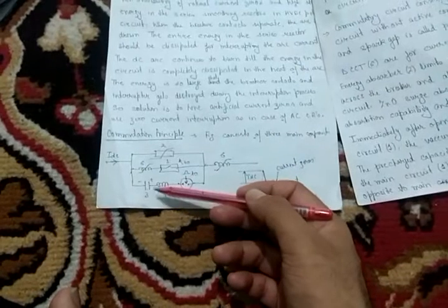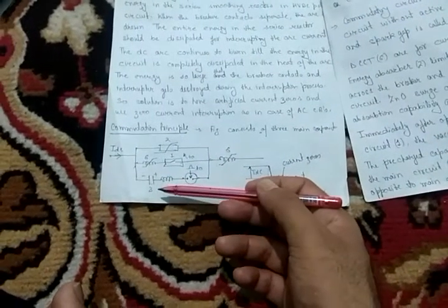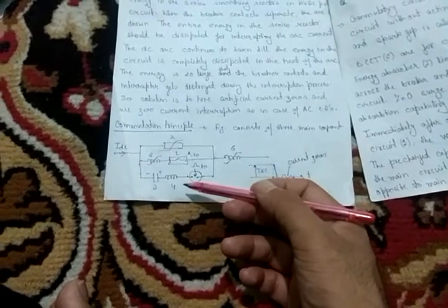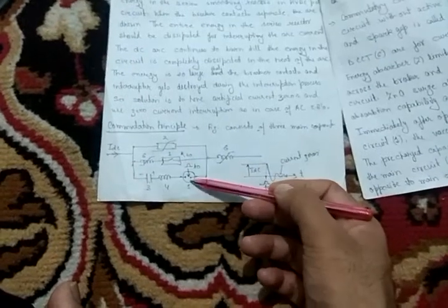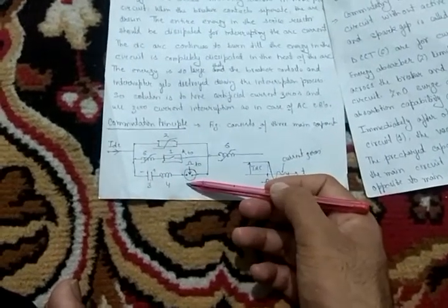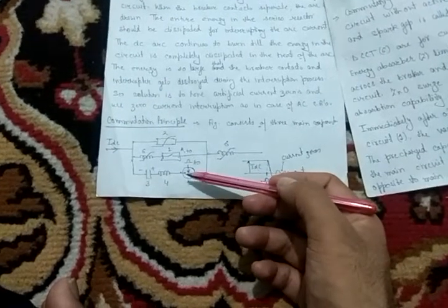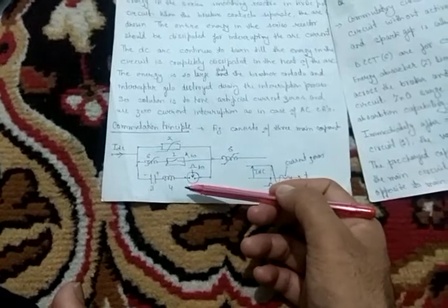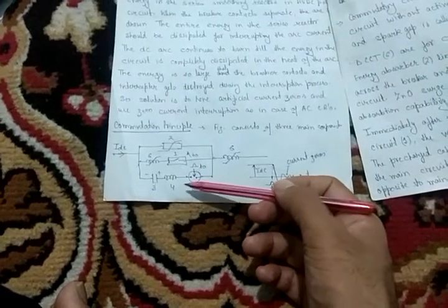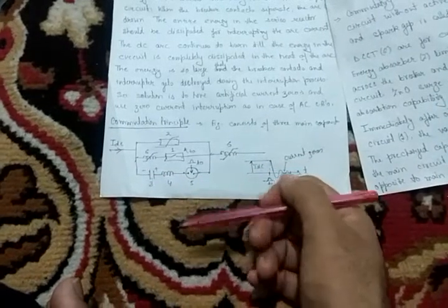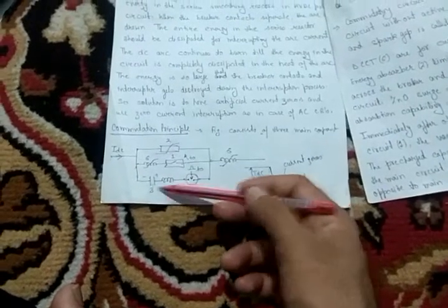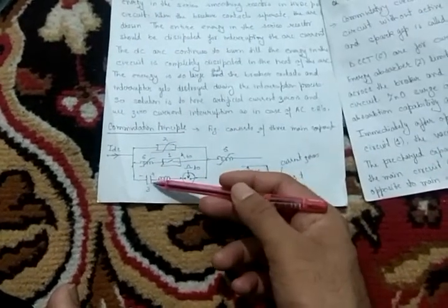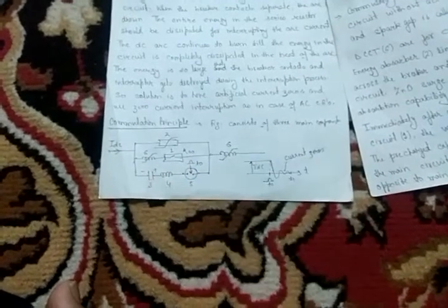This commutating circuit may be an active commutating circuit or a passive commutating circuit. In case of an active commutating circuit, active components such as a pre-charged capacitor, which means this capacitor is initially charged, and a spark gap are used. Such a circuit is called an active commutating circuit. In case of a passive commutating circuit, we have an LC resonant series circuit without active components, like we don't have a charged capacitor here.